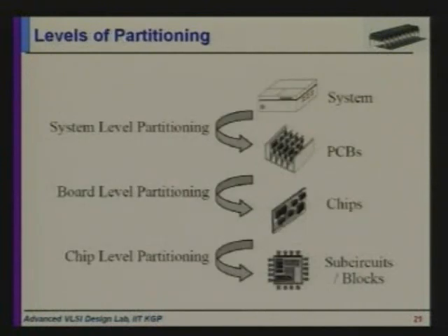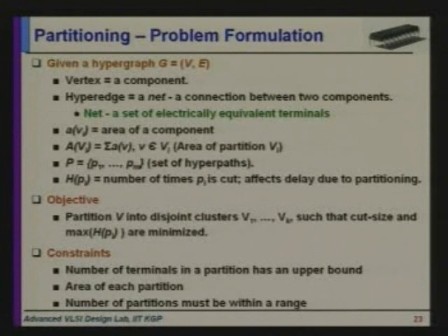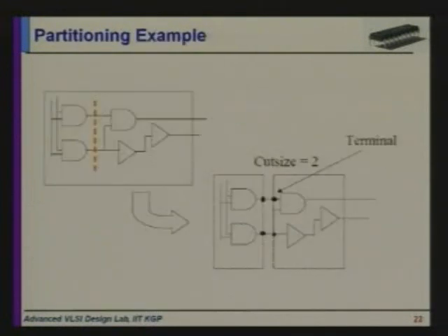Partitioning can be at different levels. When I have the complete system and I am partitioning it into a set of PCBs, it's called system level partitioning. When I partition the PCBs into a set of chips, it's called board level partitioning. And when I'm partitioning a chip into subcircuits, which we'll consider, it's called chip level partitioning.